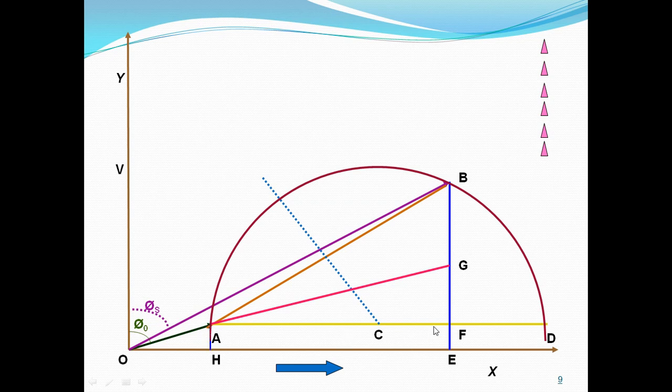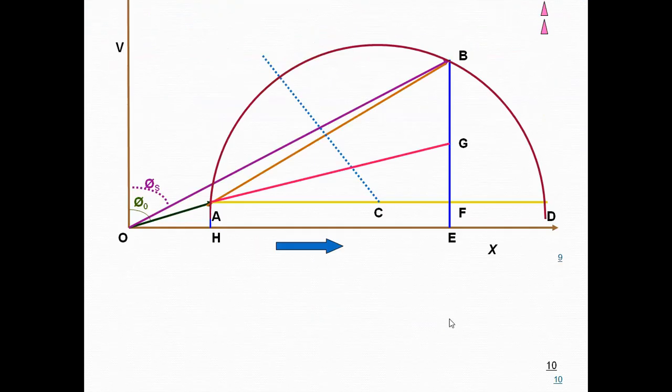So H is equal to Fe. This is fixed losses. So we have to get the point G like that. VG represents rotor copper losses and GF represents stator copper losses.